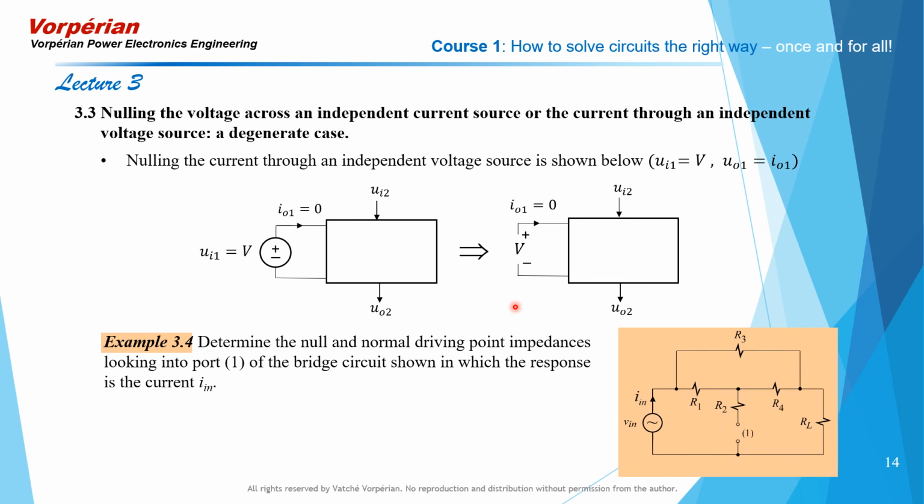And you can try this, as I say, with the simplest possible circuit that you can think of. Do it with a voltage divider. Do a voltage divider between two resistors, R1 and R2, across a voltage source V. Find the voltages across R1 and R2. Then take R2 out and replace it with a voltage source equal in value to what you get from that voltage division.